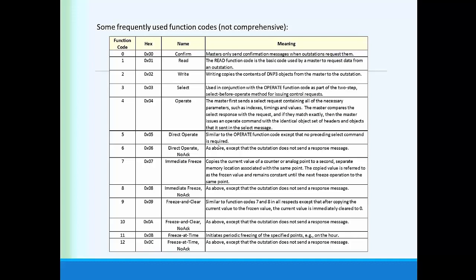And then what the master station does is, instead of reading the running counter, it reads the frozen counter. So by reading the frozen counter, you have an entire hour to read your 200 meters instead of reading them sequentially. You can still read them sequentially, but the information that you get will all be what the kilowatt hours were at the top of the hour.